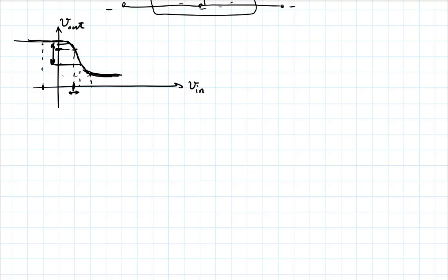Let's say, a sinusoidal signal with an amplitude of 10 millivolts that's added on top of an offset of 1 volt. So your signal is going from 0.99 volts to 1.01 volts, right? So you have some small variations around a bias point. And that's the language that we are going to use in this discussion.